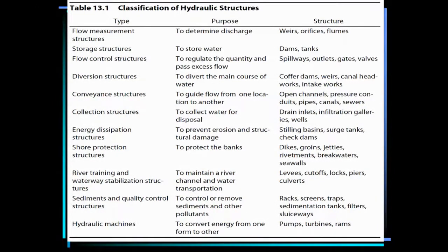Then for short, small pipelines, like the pipes for the water distribution network in our buildings, we use a particular device which is just fitted along the pipeline to take care of the surge or the water hammer. That device has some gas inside, which will help in absorbing the excessive pressure generated as a result of the water hammer.